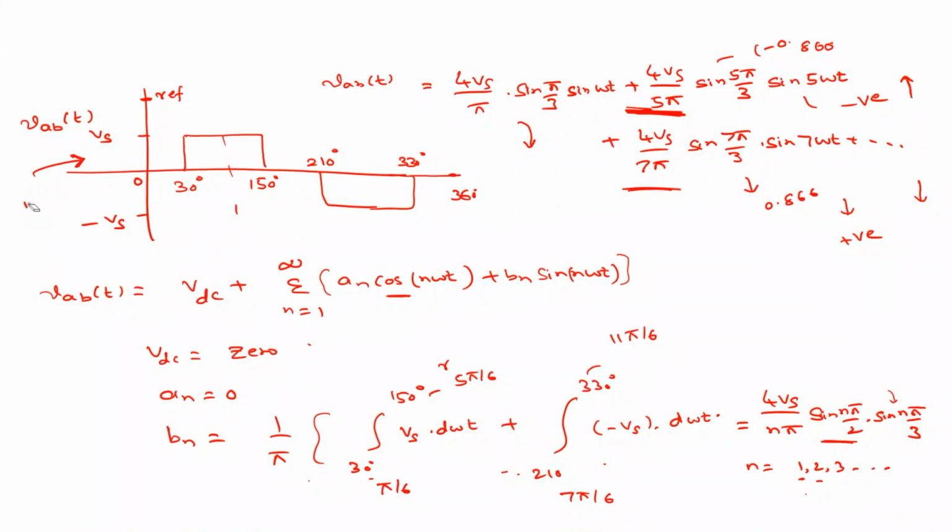So why exactly is there that 30 degree shift? Because it eliminates the third order, sixth order, and ninth order harmonics. That way you are left with the fundamental, fifth, seventh, 11th and 13th and so on. So this is producing the torque in the clockwise direction, for example, and the seventh order will produce it in the anti-clockwise direction, right? Similarly, for the 11th order, if it's produced in the clockwise direction, this will produce it in the anti-clockwise direction.